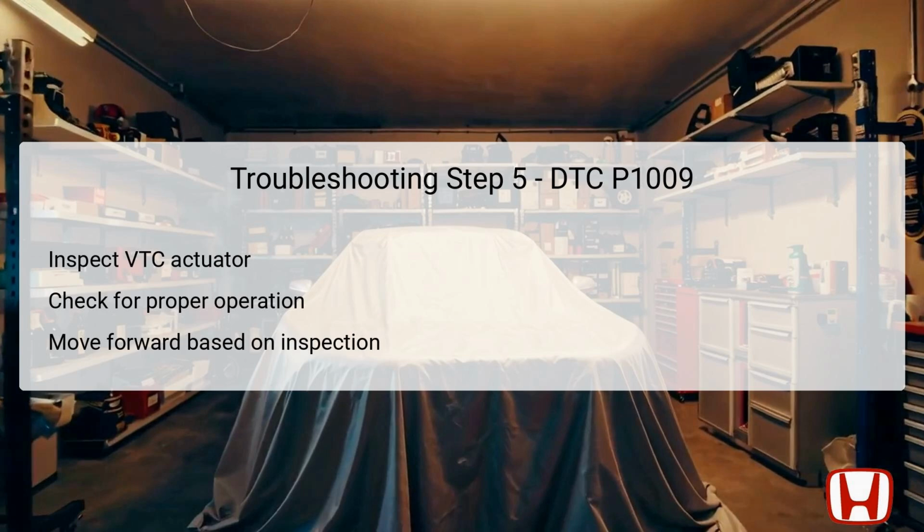Conversely, if it seems to be functioning properly, the technician should then check the entire VTC system's oil passages for blockages that could disrupt oil flow. This inspection should be thorough, as blocked passages can lead to recurring issues even after component replacements. Ensuring all parts are in working order is essential for comprehensive repairs.